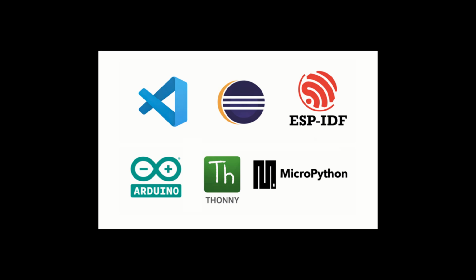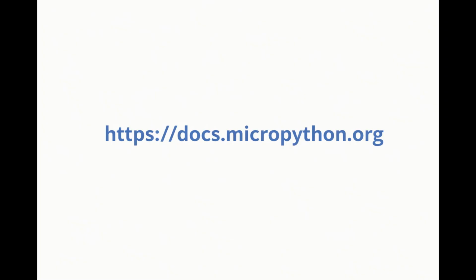However, because it is interpreted, MicroPython may not be suitable for more demanding applications such as high-speed sensor sampling, fast Fourier transform processing, etc. For this tutorial and quick mock-up to make a blinking LED using a GPIO port, we'll use MicroPython. See this URL for the documentation, along with the Thonny IDE, especially well suited for beginners, which can be downloaded from this URL.